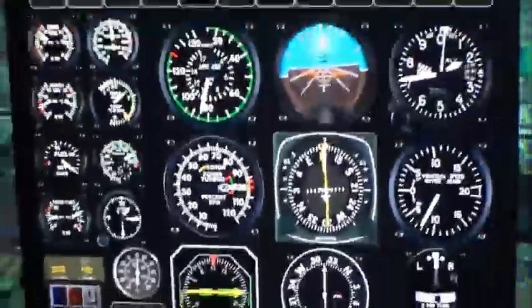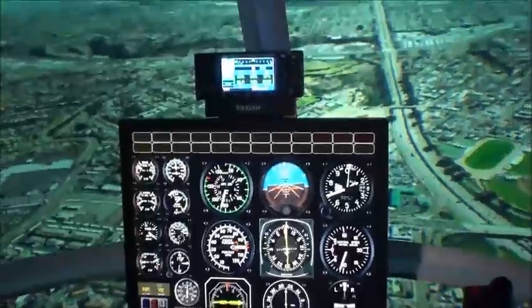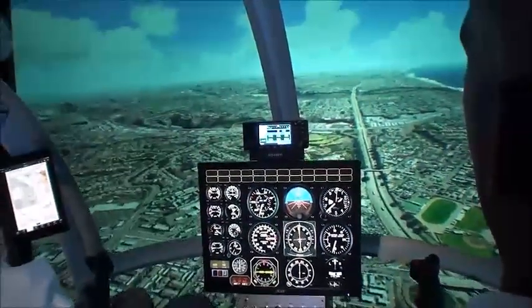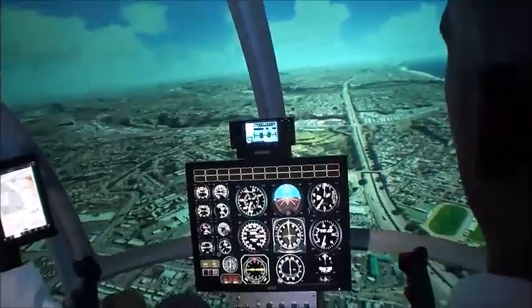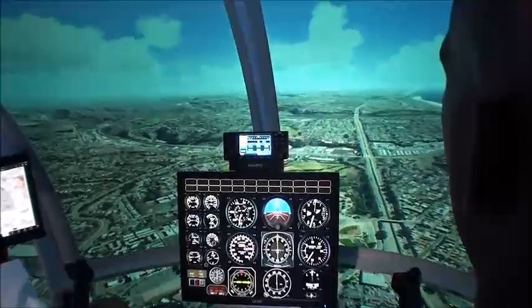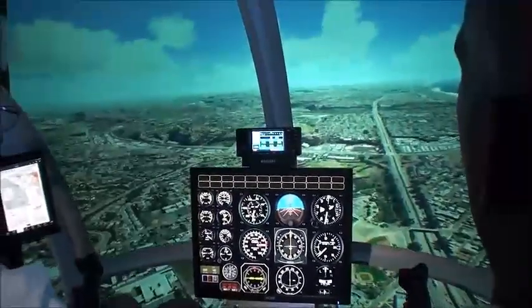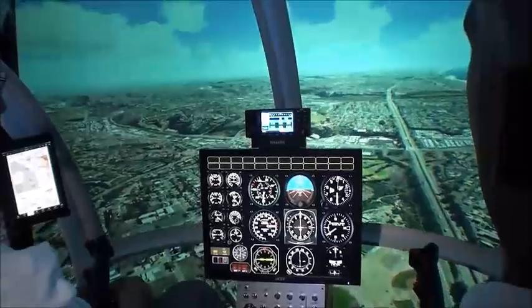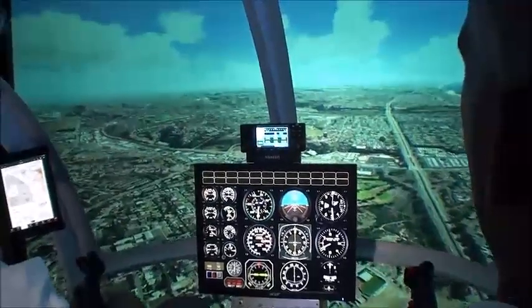Okay, we're 500 feet above minimums. The minimum is 1,300. So I need to hold 1,300. Yeah, once you get to 1,300, you need to hold it, and that's going to be actually for a few miles, because we're going to have 3.5 miles to go at 1,300.